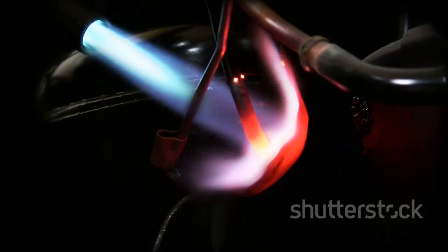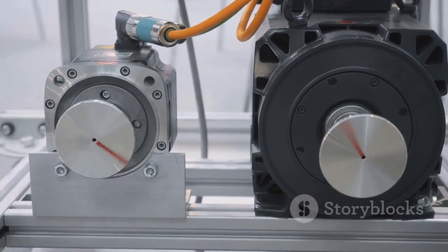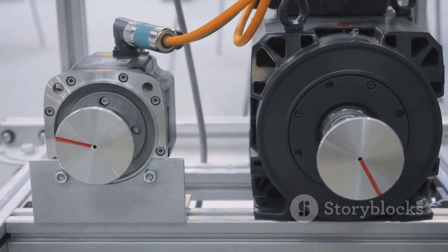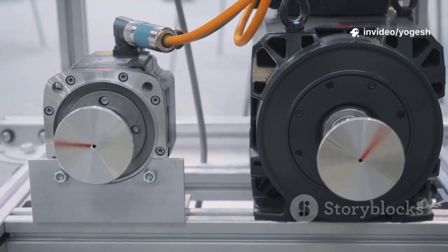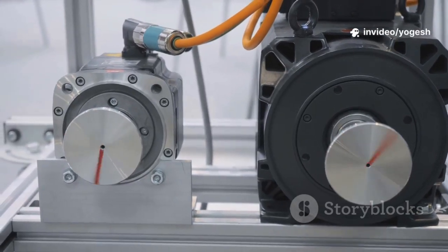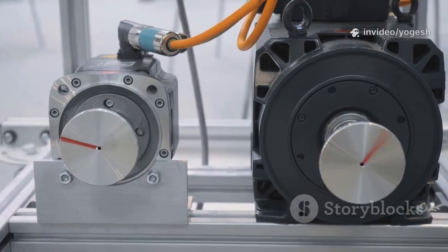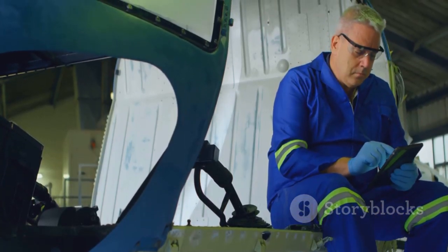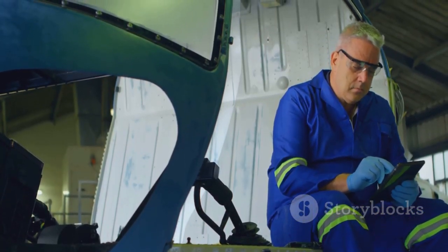Welding symbols are standardized globally by ISO and ASME AWS. ISO 2553 uses a dashed reference line for the other side, while AWS, used in the US, uses a single solid line with above-below conventions. Knowing which standard applies is critical. Misinterpretation can lead to serious errors.